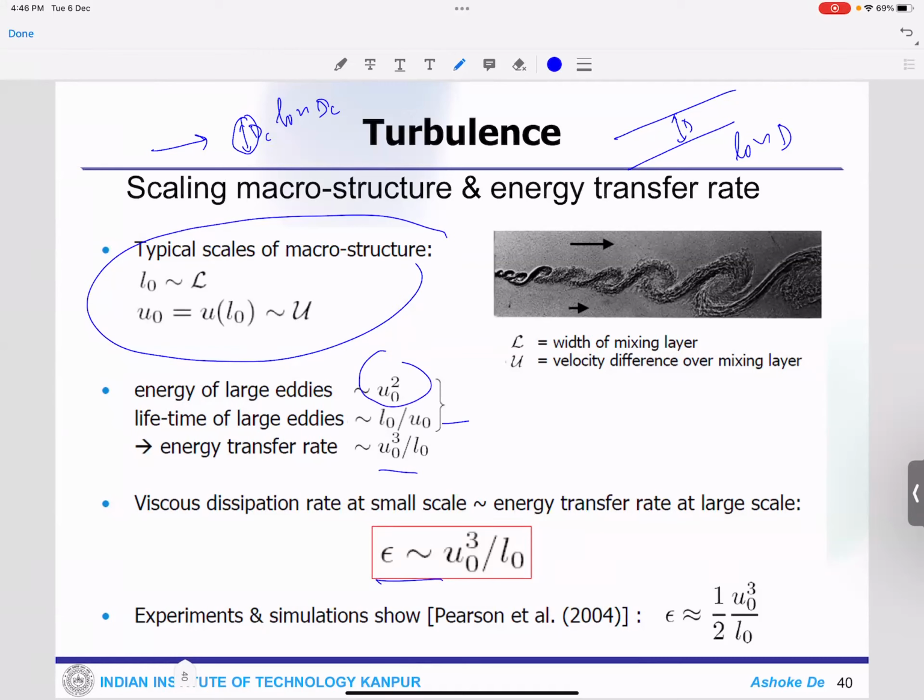So yes, the energy can also be transported across a variable density region. Yes, that is true. That is the question from Ashutosh. But there is another important thing, because when you talk about variable density flow, there will be an extra term which is going to come up, called the baroclinic production term, which is a cross product of the density and pressure gradients.